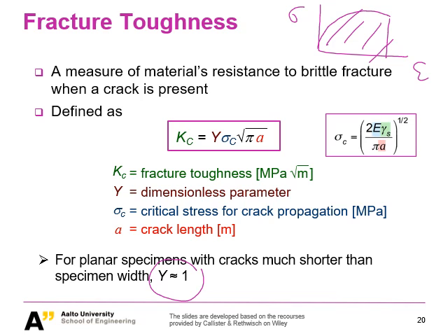We just want to know, if we have such a material, its resistance to crack is like that. So what we did here is very simple. Basically, we just took the square root of pi a, we took the geometrical part out of it, and then you keep only your material intrinsic characteristic to resist crack.